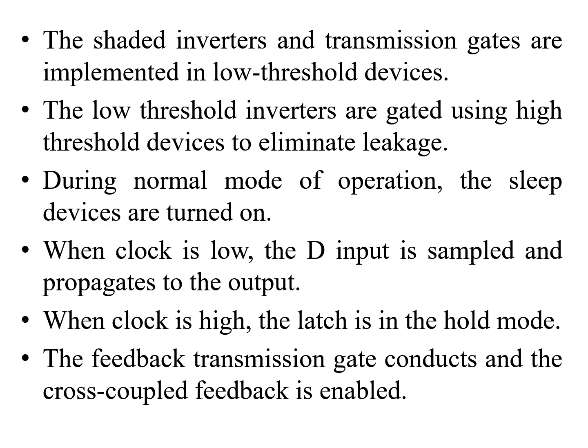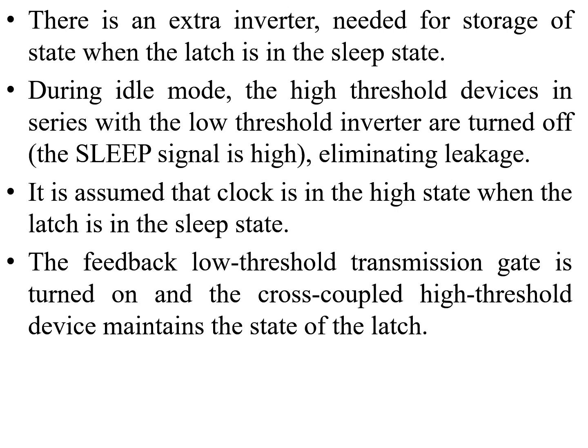The feedback transmission gate conducts and the cross-coupled feedback is enabled. There is an extra inverter needed for storage of state when the latch is in the sleep state. During idle mode, the high threshold devices in series with the low threshold inverter are turned off. The sleep signal is high, thereby eliminating leakage.